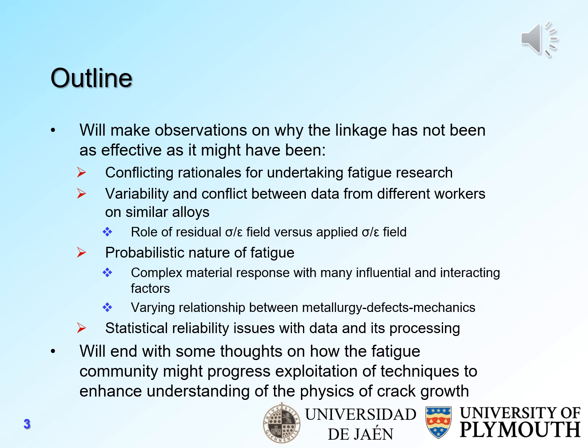And I believe that some of the reasons for this are conflicting rationales for undertaking fatigue crack research, which I shall expand on, variability and conflict between data from different workers on similar alloys and under similar conditions, probably the role of residual stress or strain fields versus the applied fields, the probabilistic nature of fatigue, where there's a very complex material response that has many influential interacting factors, and equally a varying relationship between metallurgy, defects, and mechanics. There are also, of course, statistical reliability issues with data and its processing.